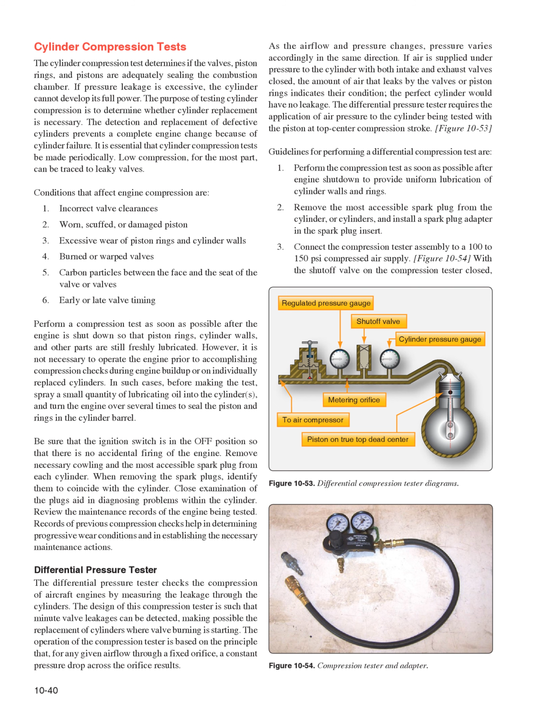Perform a compression test as soon as possible after the engine is shut down so that piston rings, cylinder walls, and other parts are still freshly lubricated. However, it is not necessary to operate the engine prior to accomplishing compression checks during engine buildup or on individually replaced cylinders. In such cases, before making the test, spray a small quantity of lubricating oil into the cylinders, and turn the engine over several times to seal the piston and rings in the cylinder barrel.